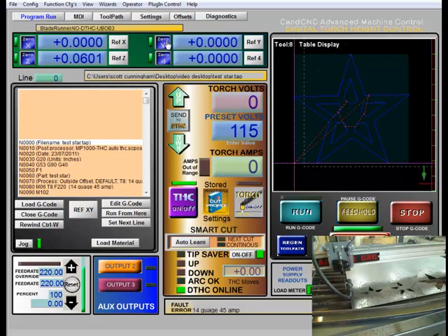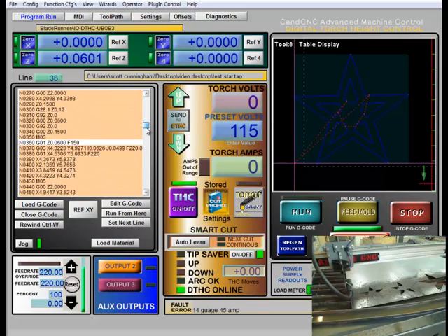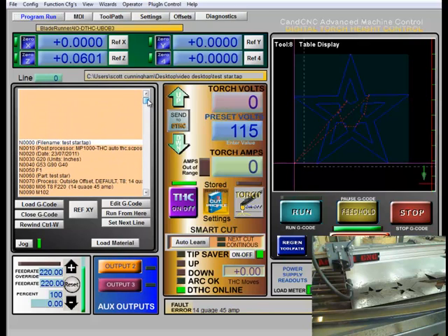So now, first off, we're going to talk about e-stops and how to recover from an e-stop error. Generally, I try not to use the e-stop, but sometimes you just got to have the machine stop immediately. If you have your machine 0 set, you can recover from that. If you don't have a machine 0 set, you cannot recover from that, because Mach will instantly lose position once you hit it, because it does not allow Mach to finish the line of G-code that it's on. What it does is it stops abruptly, and the buffered G-code that has already been sent out, Mach loses that. So these positions are no longer correct. The difference between e-stop and feed hold is feed hold allows Mach to finish that last buffered set of movements, so it doesn't lose position.